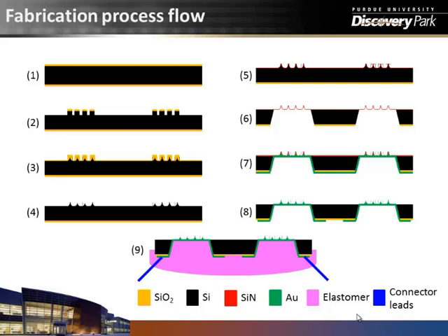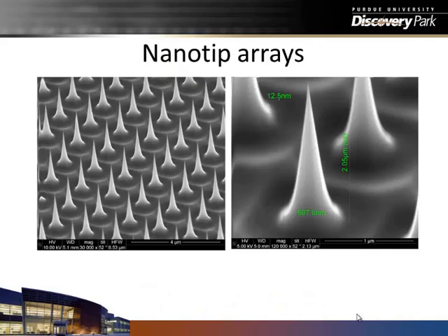We then isolate these two electrodes. And the reason we do that is because our measurements are done in a differential mode. So we provide 2 electrodes per die that we make. So this isolation gives us 2 electrodes. Remember, this is high resistivity silicon, so we get a good isolation between these 2 electrodes. We then bonded wires on the back side and then covered everything on the back with this purple insulating elastomer to seal the back side.